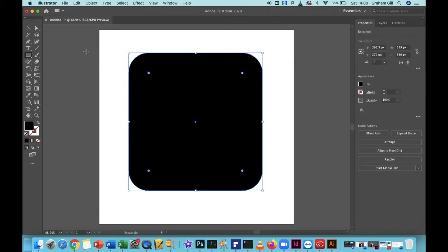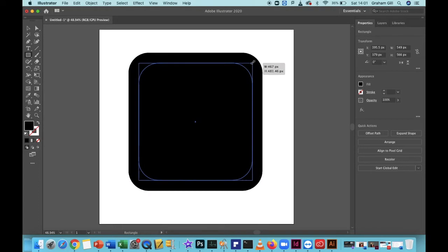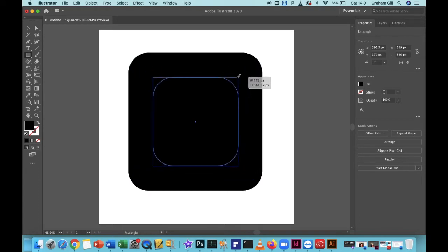Now we need to resize it, but if we try to resize it now, it will drag from one corner only. So we're going to click on the corner slider and hold the mouse button down, or trackpad button, and then hold Shift and Option keys on your keyboard together. While holding these keys down, drag the slider inwards and it resizes all sides of the new rectangle. Keep holding the Shift and Option key down and then release the mouse or trackpad button. Now you can release the keys and we have a new second rectangle.